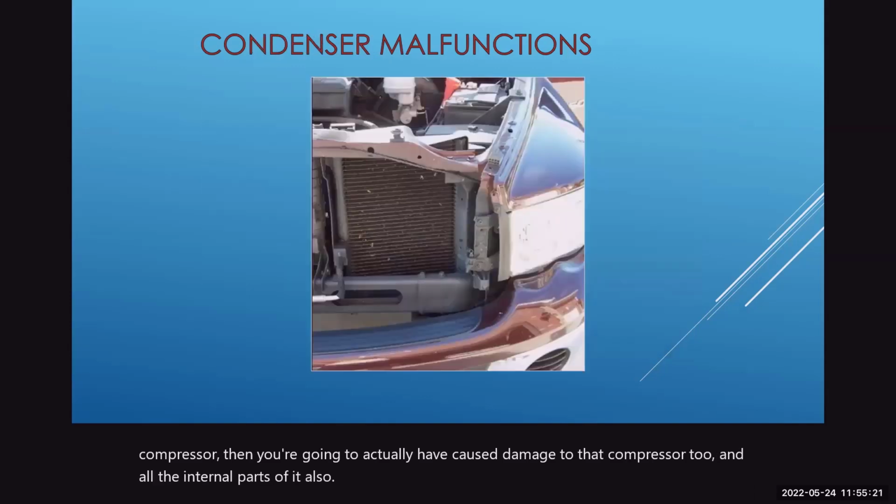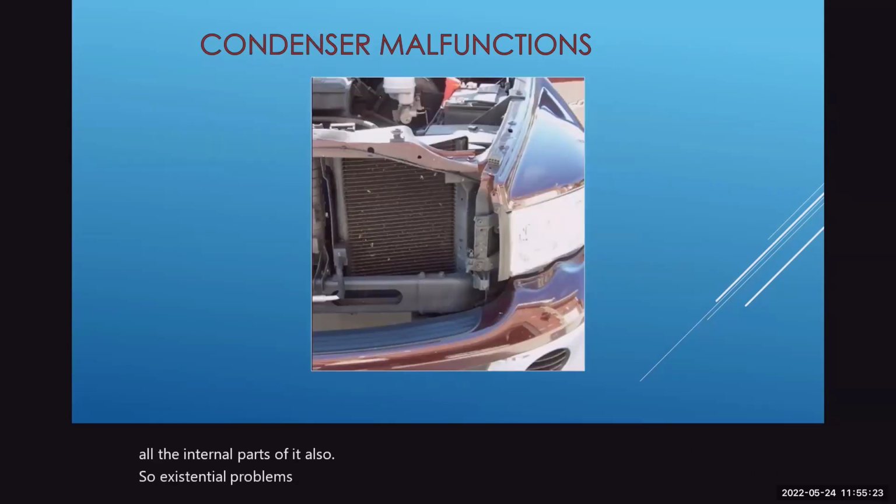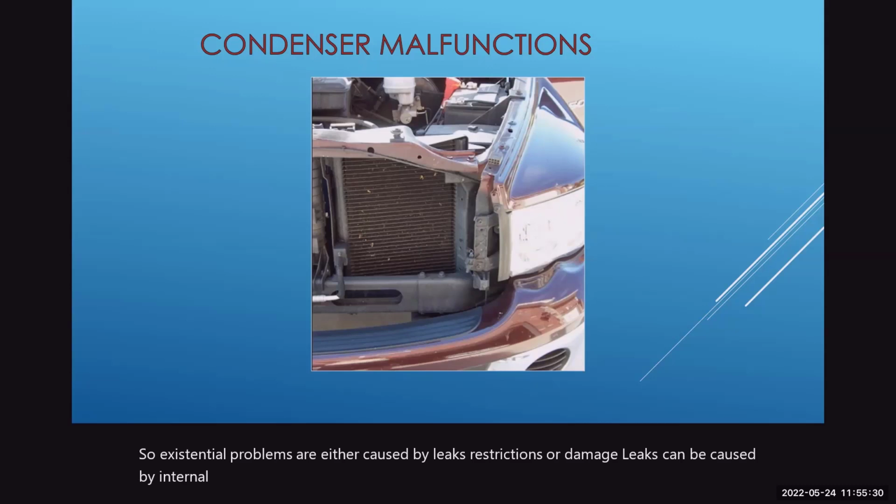Condenser problems are either caused by leaks, restrictions, or damage. Leaks can be caused by internal or external corrosion from road salts and other environmental pollutants. Leaks can also be caused by loose or broken mounting hardware.